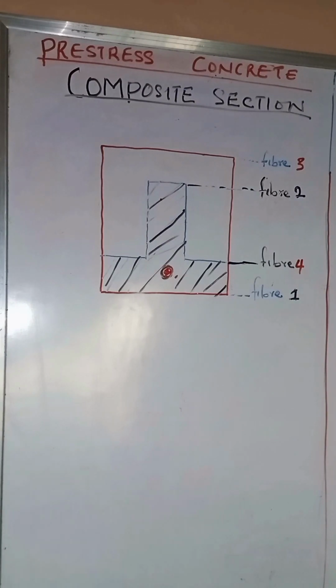So now we are going to go on to look at several cases when it is not propped. Apart from the propping, in the design principle, we are going to be considering two basic principles. A system whereby we have the precast beam not propped, and when the precast beam is not propped, which I said is what we are going to do because it is a common method of construction.